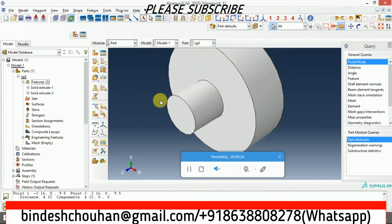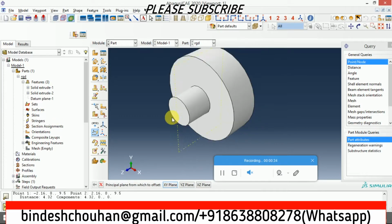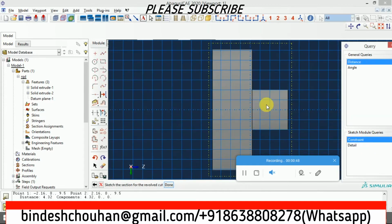So let us draw. For that, first you need to draw a plane. I'll draw the YZ plane. So we have now the YZ plane. Next you long press this and select the revolve cut. From here select the plane. Next select any of the lines.